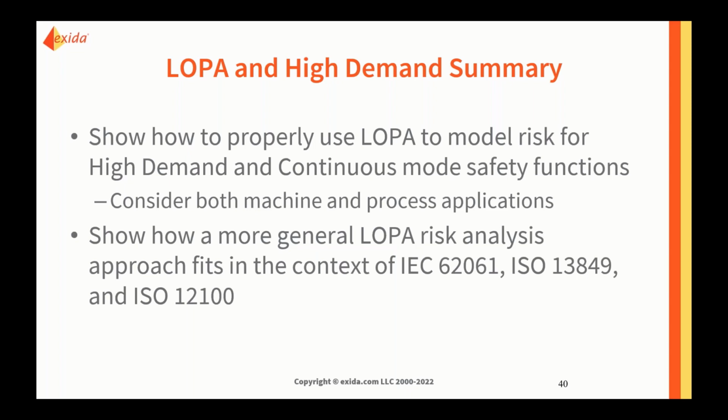The problem comes when a SIF is actually a not too high demand, for which we might need to consider a PFH to follow the standard, but which we might look at as a functionally independent protection layer. Now, that is an interesting situation, and this is where we are doing a vast simplification of the math.